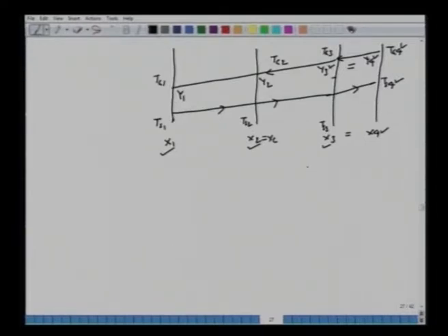All right. Now, what things are not given to us? Tg1, Y1, Tg2, Y2. These you have to calculate, along with Tg3; Y3 is given to us. So what is the approach? First, before we make any calculations for theta, we should try to make an overall enthalpy balance and an overall moisture balance, or balances over certain segments, so that we evaluate as many of the quantities as we can.